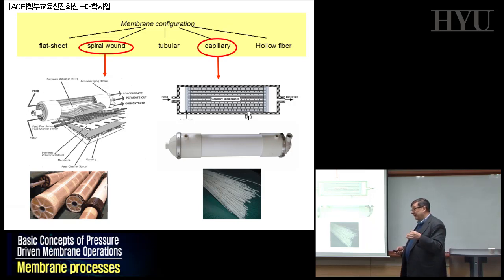Now this problem in part has been solved because people are becoming more expert. Years ago, it was terrible. People were using hollow fiber because they said there's much more surface, etc., in a compact system, you save. And they destroyed the operation because of fouling, biofouling, and big pressure drop across the system, etc. So these are the different kinds of configuration existing. Each one has some specific properties which are convenient for specific separations.